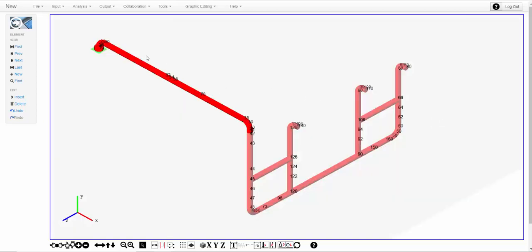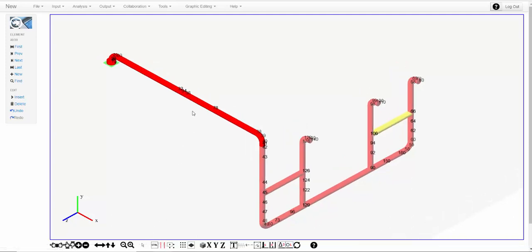So now I put this back in 3D mode. I've drawn all of my pipes. I just have to do things like change the types and the sizes and things like that. So now I'll create my valves. So this one's going to be a valve. Okay, put myself out of draw mode here. Okay, so select here, control click, double click, control double click, and so on for each one. These are all going to be valves.